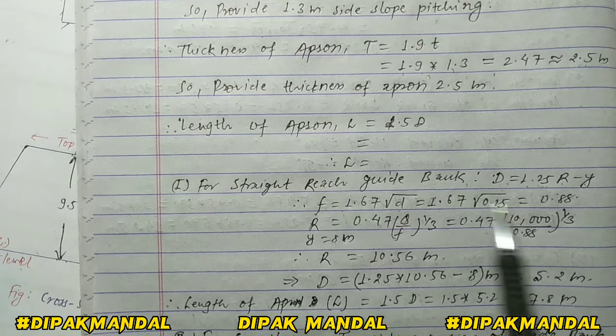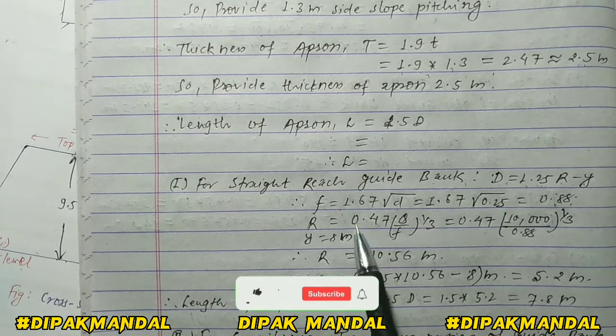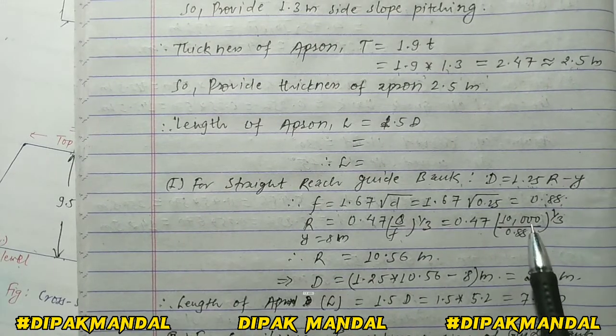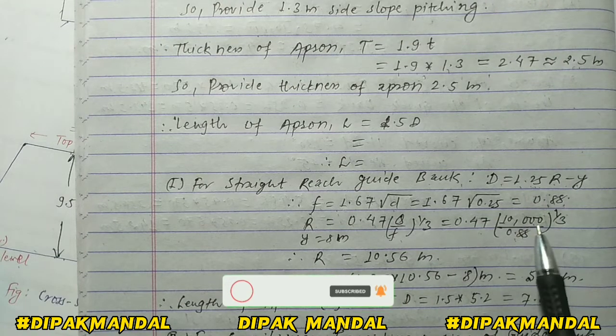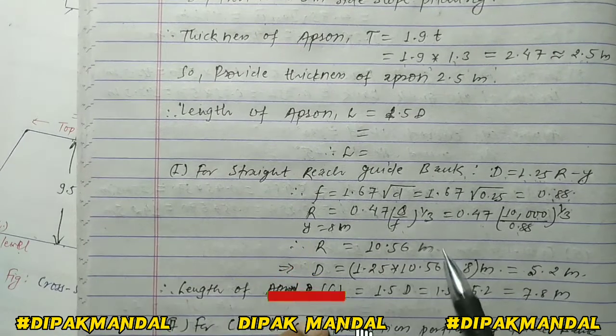So the silt factor f becomes 0.88. Now we have to calculate the value of R equal to 0.47 root under (Q by f) to the power 1 by 3. And Q is already known, and f is 0.88 after calculating this value. Okay, and this value gets 10.56 meter.